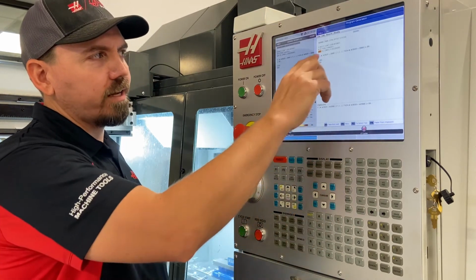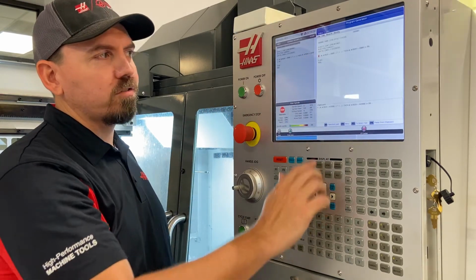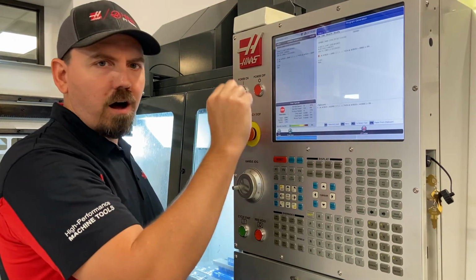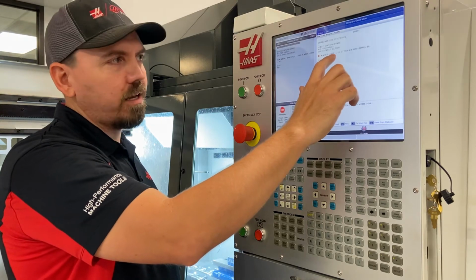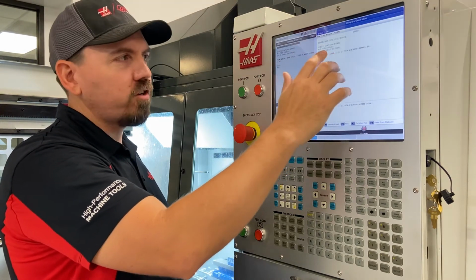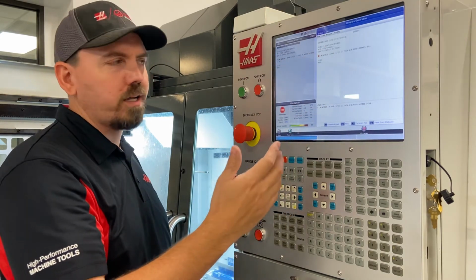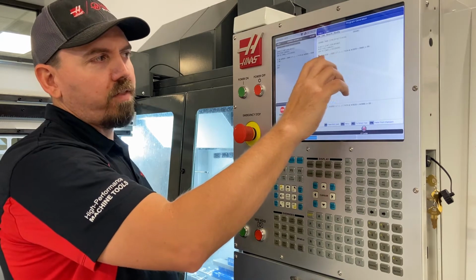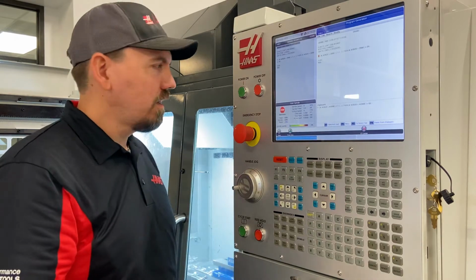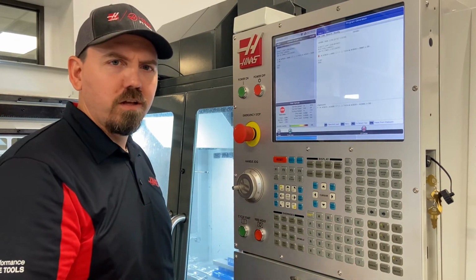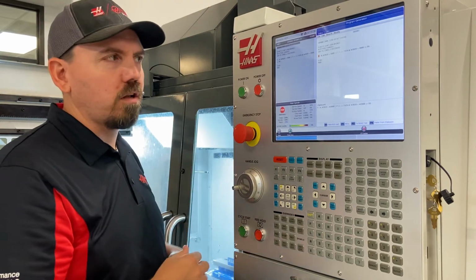I've got to dwell for 2 seconds to allow the tool change to complete the cycle. Once that's done, I've written a macro statement that checks the existing offset of the tool currently in the spindle. If that tool is less than, I put 1 inch, you can always change this. Maybe you can make it equal 0, but I figure I would probably never have a tool less than 1 inch, so that's a good starting point. If that is the case, then set that tool offset value to 99 inches. I think this machine only has 20 inches of travel, so 99 inches positive would over travel and cause an alarm.